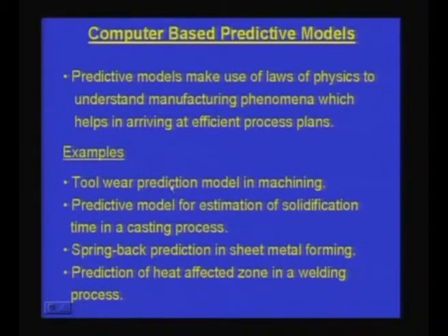For example, a process planner who is preparing a process plan for a component which has to be machined would be interested to know the tool life. Suppose I am using a tool where there is an insert, and this insert has to be replaced after a certain time.